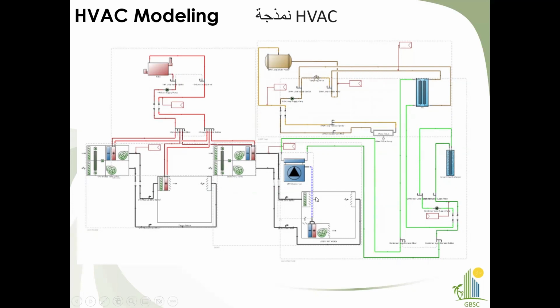So we can model chillers, we can have all the set point managers, we can control humidity, we can control air temperature, or any kind of input which is there in the design. It can be modeled, and we have pre-made modules for most of the possible systems, from radiant system to underfloor air distribution system to VRF and central chilled water system, air source heat pump. So all those things, we don't have to model from scratch. We can do it from scratch, but the basic layout is available within Design Builder, and we can use that as a starting point to develop our model further.